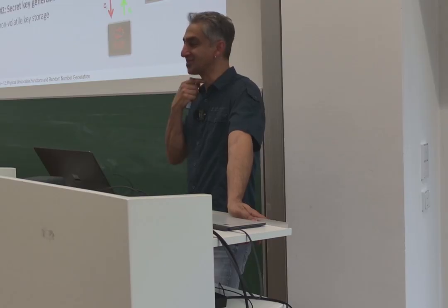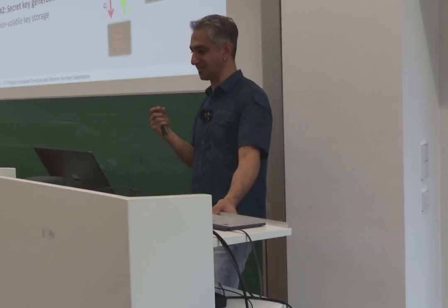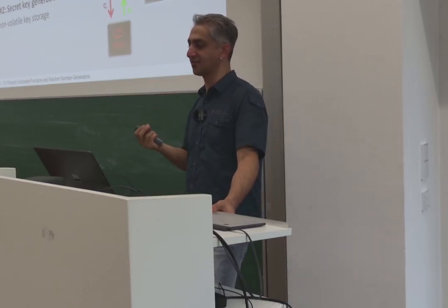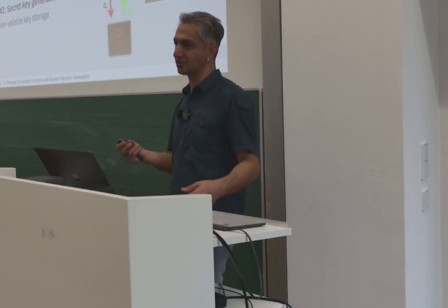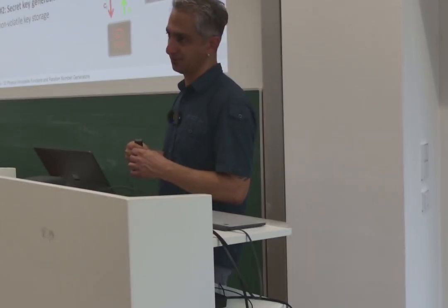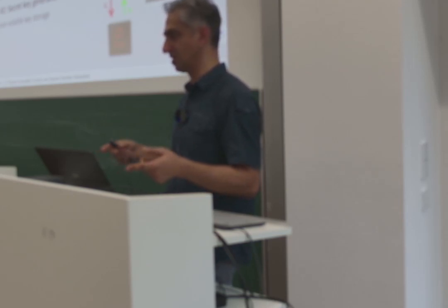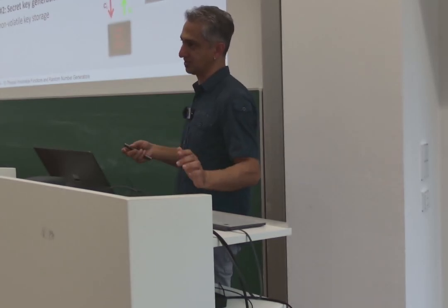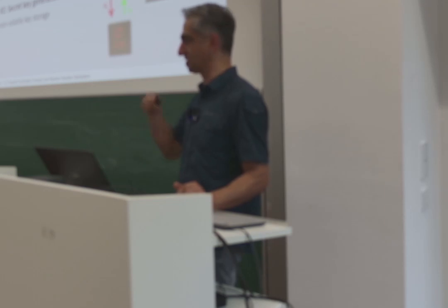Another application is to generate secret keys. It's not the challenge-response pairs, but a fixed set of challenges that are used inside the device to generate responses, and then this response goes to a fuzzy extractor and error correction to generate the secret key. In this way, you do not need any non-volatile memory. The key is generated by the device, and every key is unique to the device. This will be, for example, the secret key, and then the public key is generated inside the device and sent outside, and then the authentication can be performed.